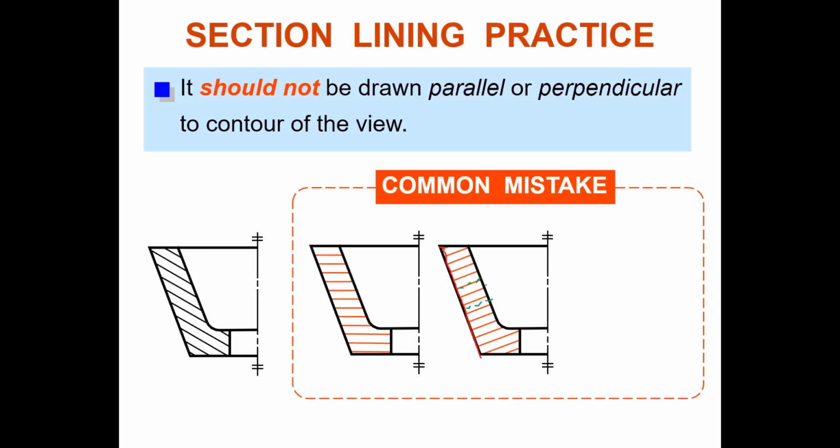Yes, understand it. The direction of that hidden line of the drill through hole, for example, is parallel to your section line, right? You cannot distinguish. Sometimes they overlap. Try to avoid this. Clear, class? Sometimes your hidden line and your section line overlap each other. So your section line overlaps, replacing the line of the hidden line of this drill through hole.